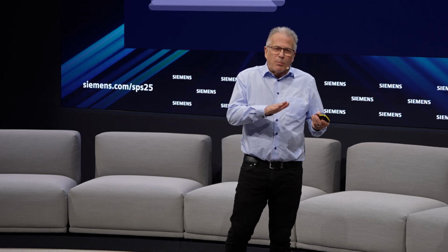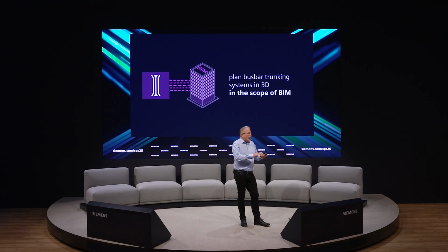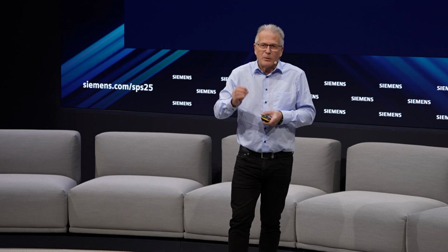And the Simaris busbar plan is a Revit plugin, a plugin for Autodesk Revit, and a standalone version is also available, the Simaris Sketch. Here you plan the geometrical size of a busbar trunking system. You make the planning through the building, and you are creating the digital twin with it. So there are then comprehensive tools to make the collision tests, to check that everything is okay across all the trades.